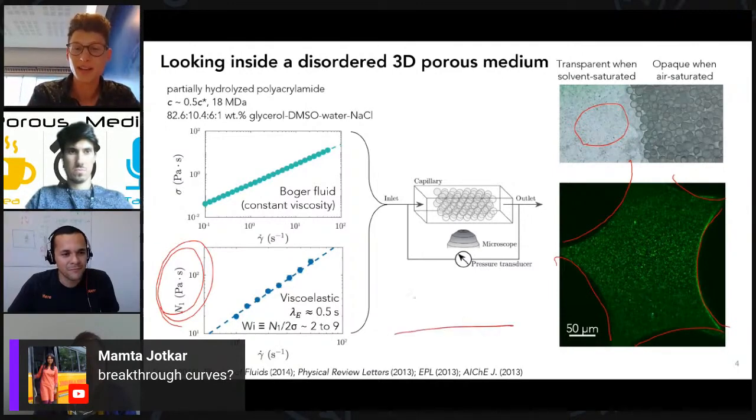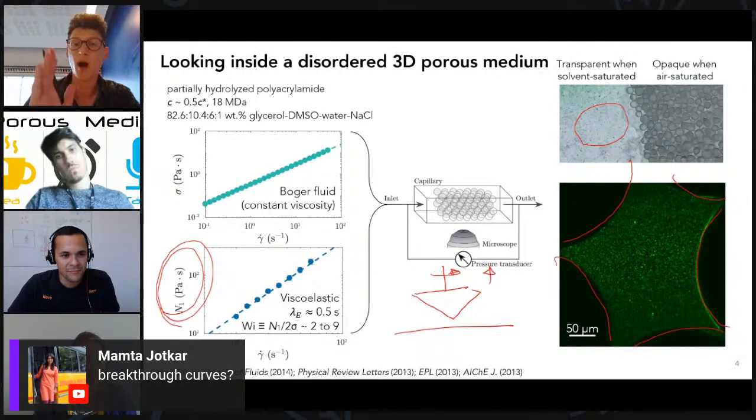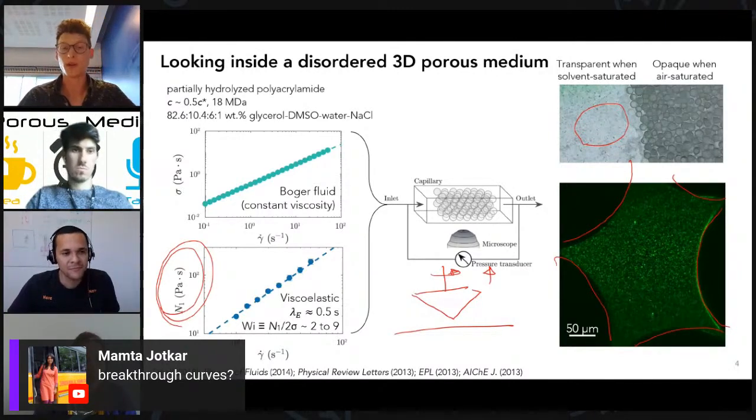What that means experimentally, if I put this on a cone-plate rheometer and I'm spinning it, is that you measure a tangential shear stress. You also measure a normal force pushing up on the cone. That is a result of the polymer elastic energy being stored and released in the vertical direction. You can measure that as one metric of this elasticity. You could also measure G prime and G double prime, and you would find that this had a significant storage modulus as well. Does that answer your question? I'm not sure. It does.